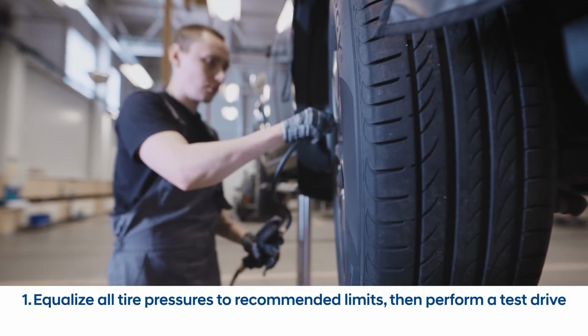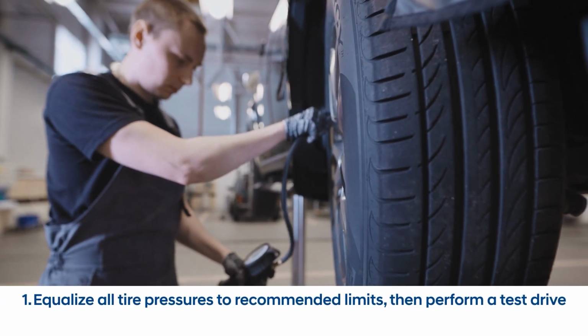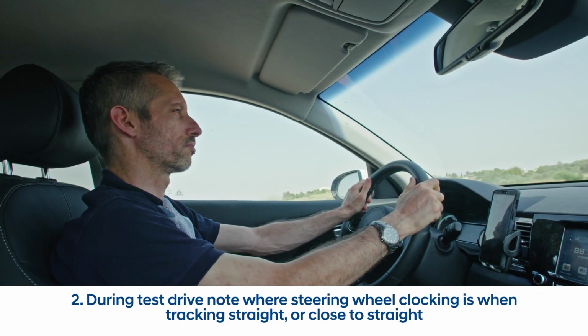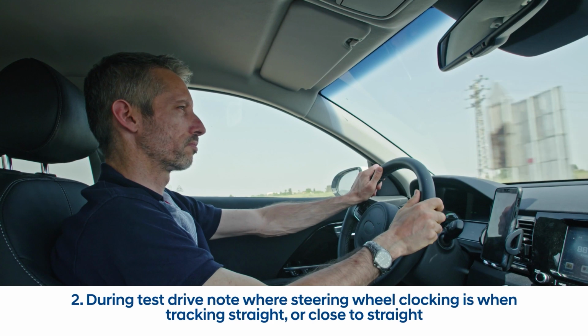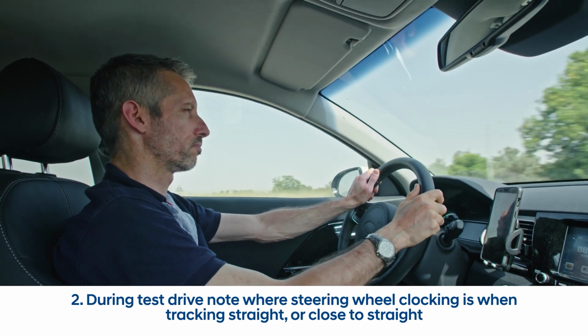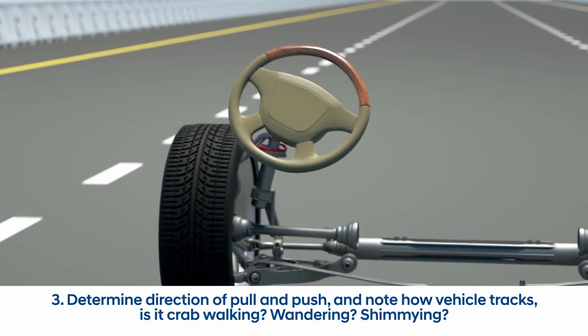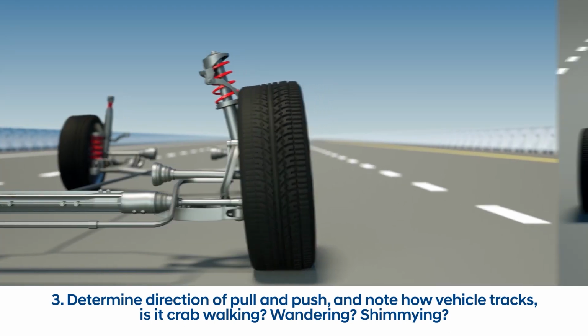Now that we have reviewed alignment geometry, we will review the 12 main steps of performing a four-wheel thrust alignment. 1. Equalize all tire pressures to recommended limits, then perform a test drive. 2. During test drive, note where steering wheel clocking is when tracking straight or close to straight. 3. Determine direction of pull and push, and note how vehicle tracks.